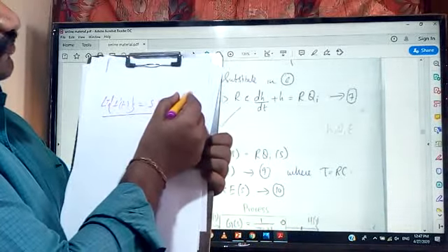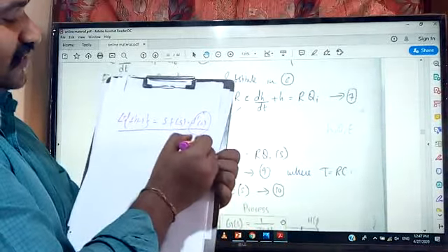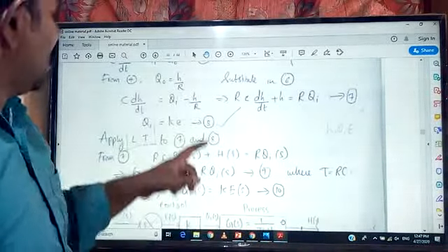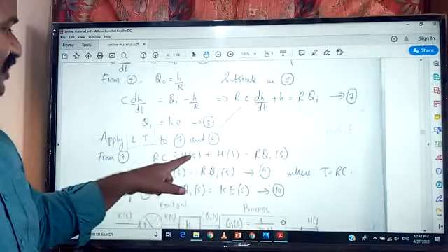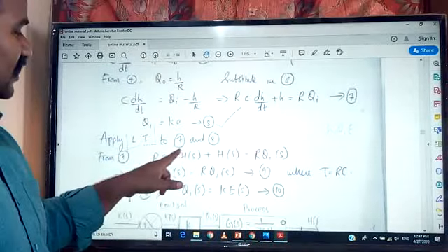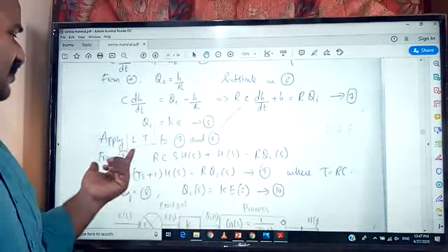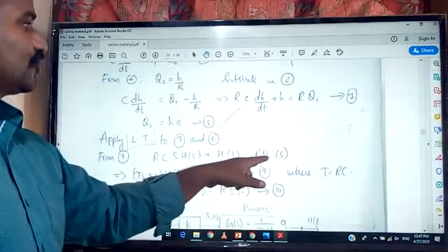Here I am assuming that the initial conditions are equal to 0. So as I am applying the Laplace transformation to the first order system, it is going to be s into H of s. RC is always constant, so plus H of s equals R Qi of s.